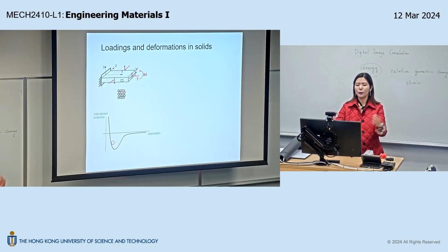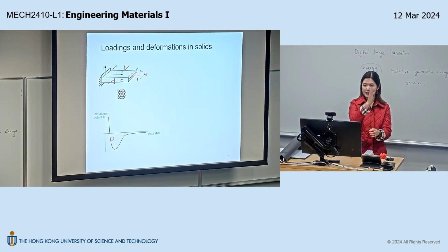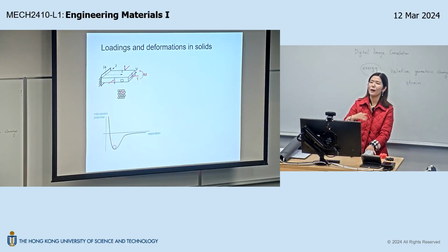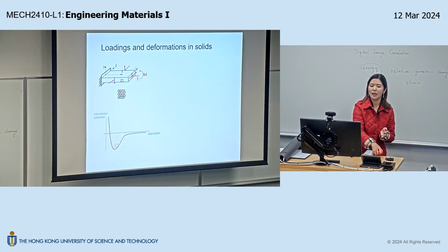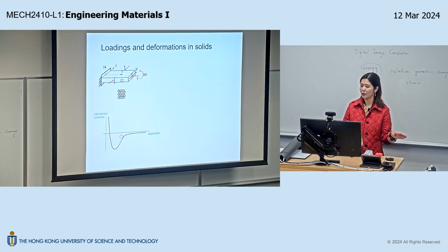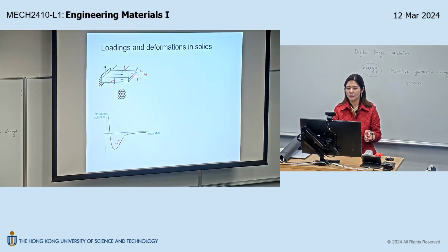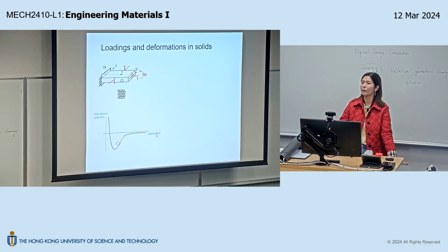And now if we pull it or compress it, okay, we will change the separation. And if such a change is small enough, means this atom just hops from left to right, right? Cannot escape from the energy well, then this material still maintains its integrity. And if we remove all the force, it will go back to the equilibrium. If the force is too big that the atom escapes, then it completely separates.